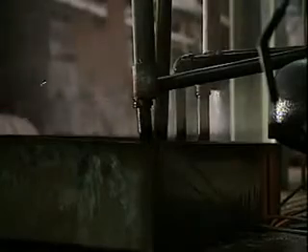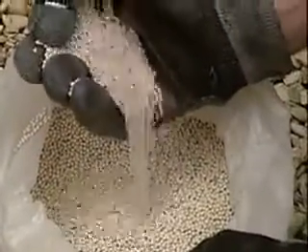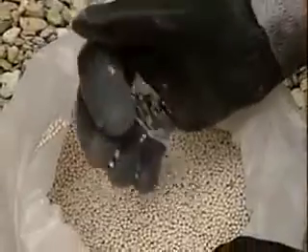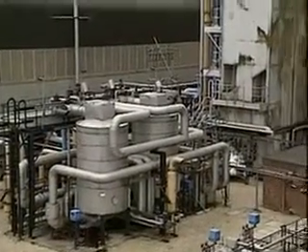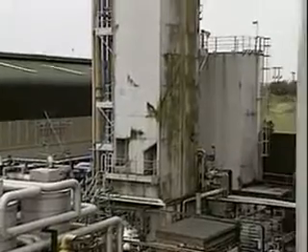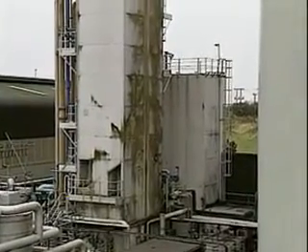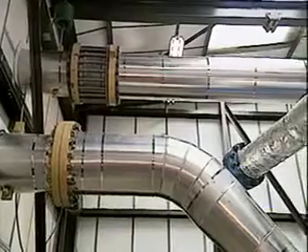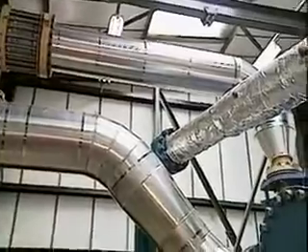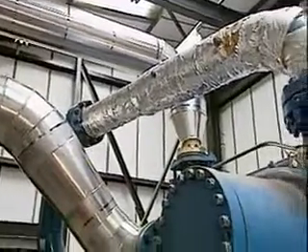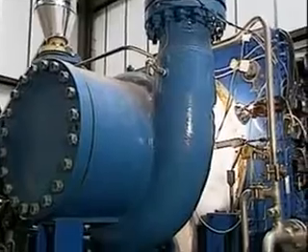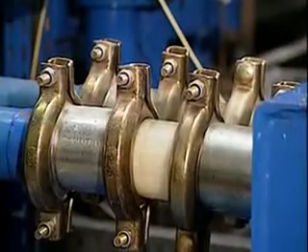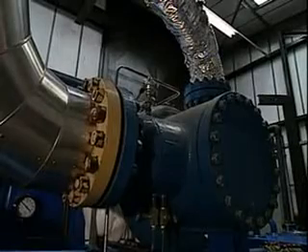The cooled air passes through chemicals which absorb the carbon dioxide and any remaining water. Further cooling takes place in a heat exchanger using cold gases from the distillation column. The air is cooled even more by compression followed by expansion. The energy from the expanding gas spins a turbine, and that in turn provides some of the energy for the compressors.